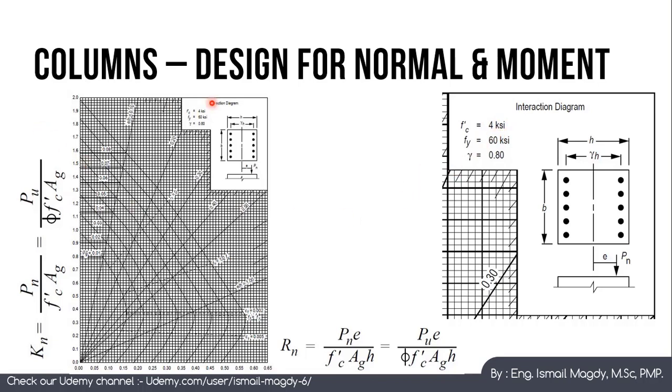In order to use this interaction diagram, we need to calculate the horizontal component of this graph and also the vertical component. The horizontal component, or what we call Rn, equals Pn multiplied by e, which is the nominal moment, over f'c multiplied by Ag multiplied by h. Pn is the normal force and e is the eccentricity, which also represents the moment. Or here, if you have the ultimate moment, then it is going to be divided by phi multiplied by f'c Ag h. Using this equation, you can calculate Rn, which is on the horizontal axis here.